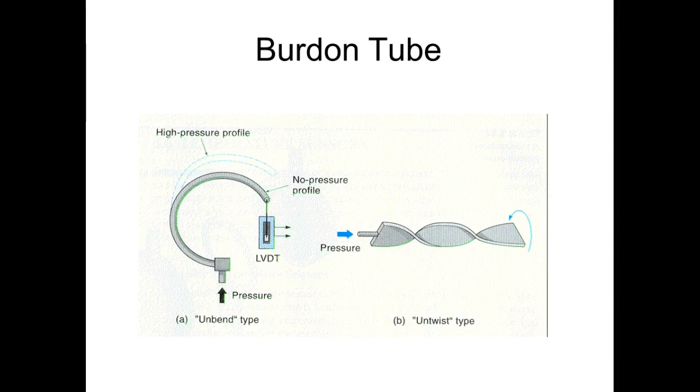So these are Bourdon tubes. We have a thing that's shaped in a C, where we have something twisted or helical. We put pressure into the tube, right? You understand? And then it's going to go around the C. The pressure is going to generate force, and that force is going to try to create a motion. The motion here is it's going to try to make the tube straight, come out of the C. Pressure would cause it to straighten up. The vacuum would cause it to come this way, right? Understand that?